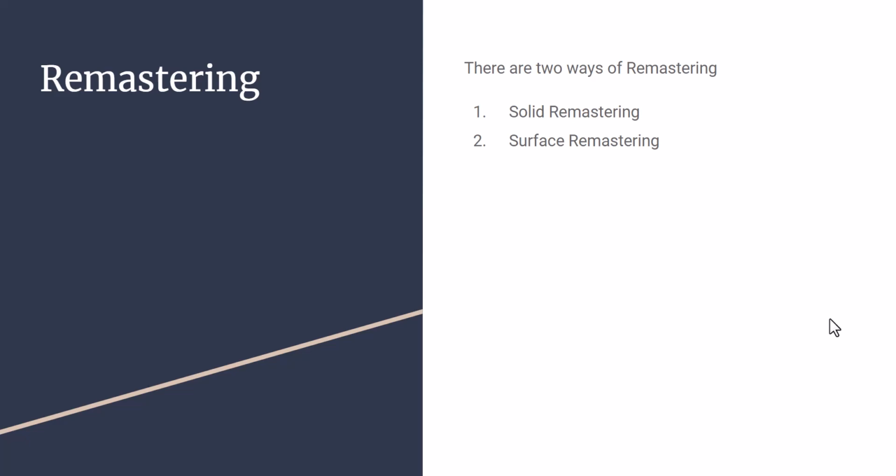We will take the references from the outer surface and start creating the outer surface. Or if a surface is given, then we can extract the geometries and construct the outer surface. Once that outer surface, a single parametric surface, is available, we can apply the thickness for converting it into a solid.